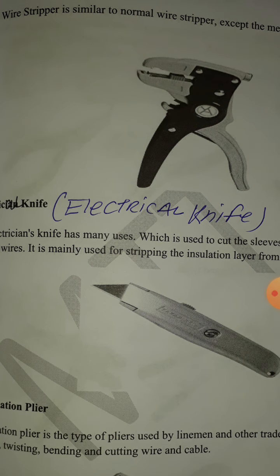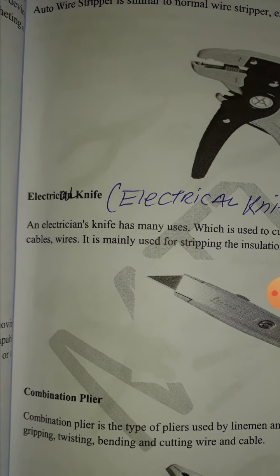This is for safety purpose, only inside conductor insulation is needed. So that time you can use an electrical knife to remove the outside insulation of the long electrical cable, and for insulation removing you need an electrical knife.